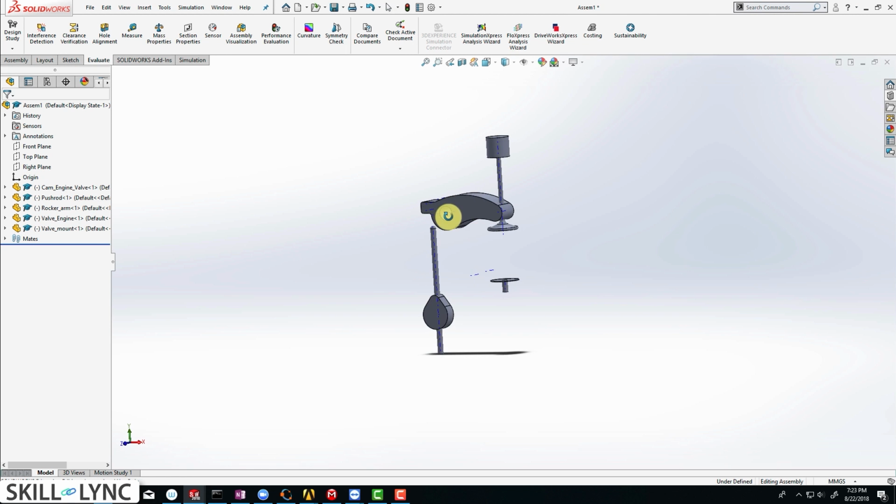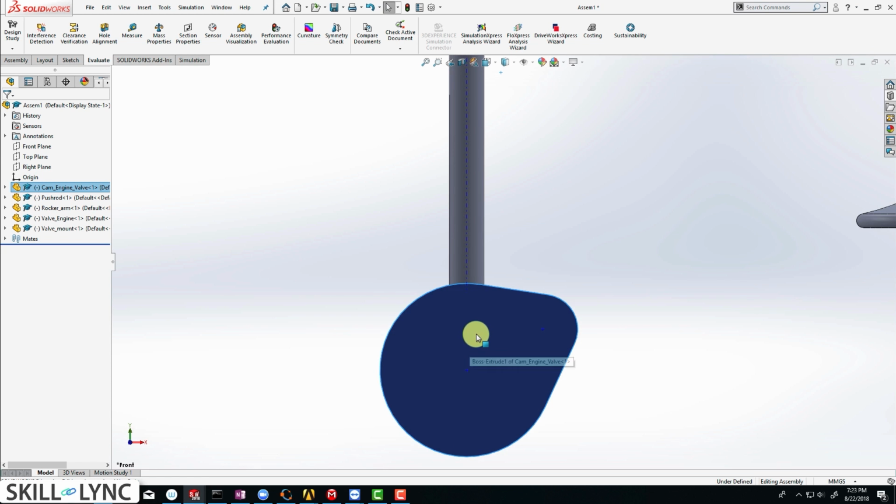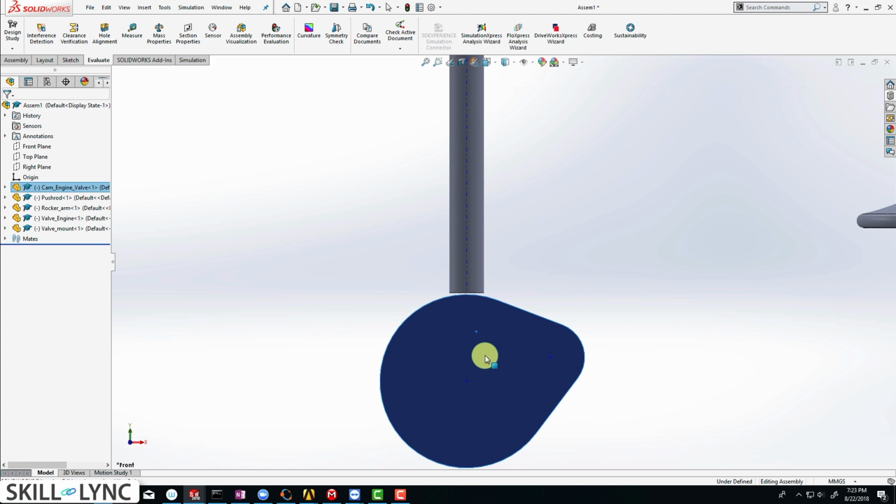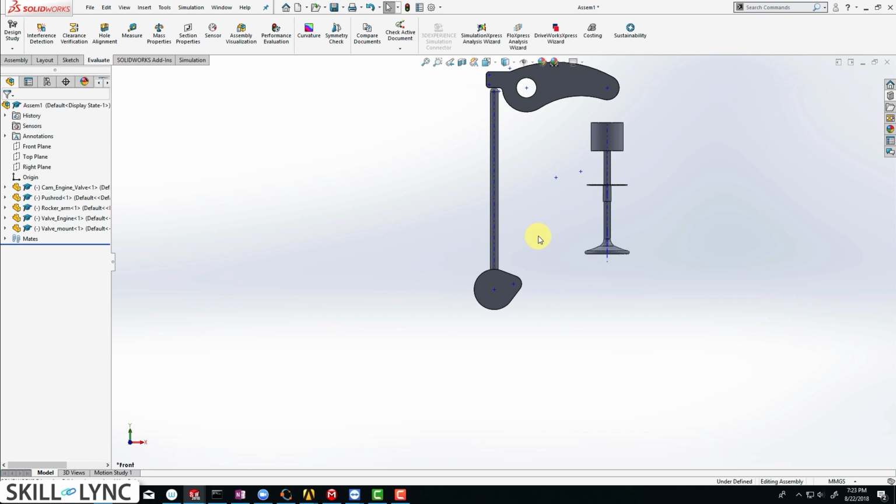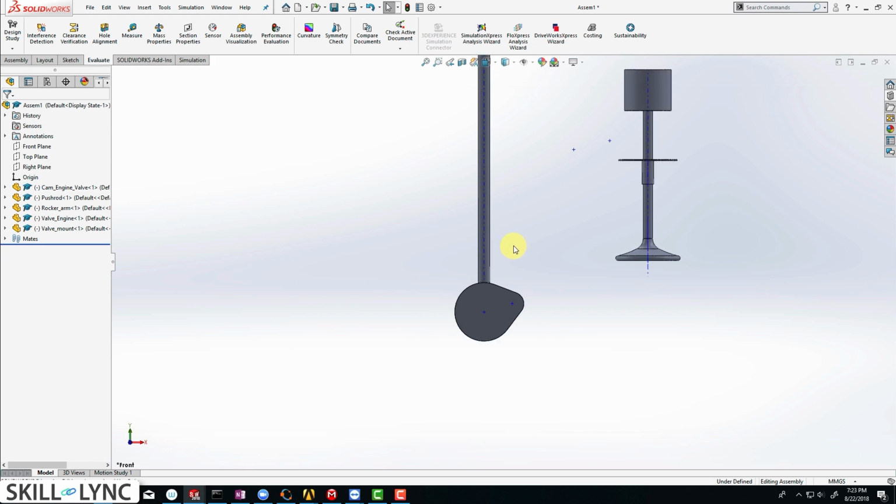Now you can just drag out the valve, and we should be able to coincide these two axes. Let's select axis number 1, axis number 2, make sure Control is selected, and click on make coincident. Now let's take a look at the geometry from the front plane, and let's click on this and push it. Because of our constraints, it's going to perfectly move in the vertical axis. Similarly, we should be able to rotate the cam and drag it exactly vertically down. Now we are manually setting up the position, so make sure that you see a very small gap, right?